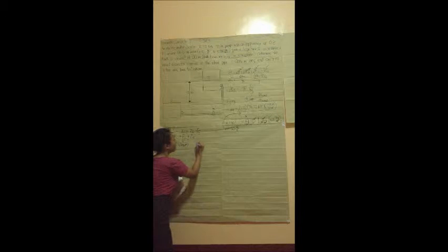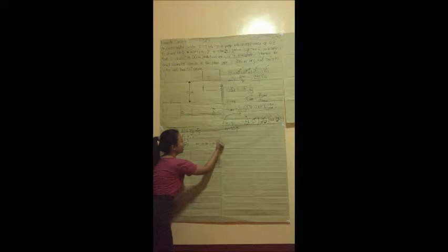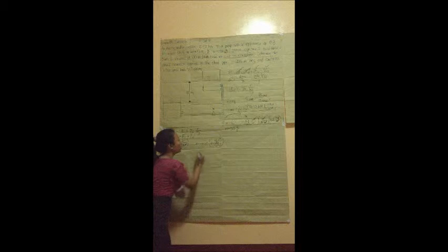So Kc has the formula of 0.55 times 1 minus d3 over d1 squared. Take note that the diameter in the numerator is always the smaller diameter. And we can say that here, 3 has a smaller diameter than this one. And from the figure, we can say that the diameter of the large tank 1 is much larger than the diameter in our reference point 3. So we assume this to be negligible. And we are left with the value of 0.55 for Kc.